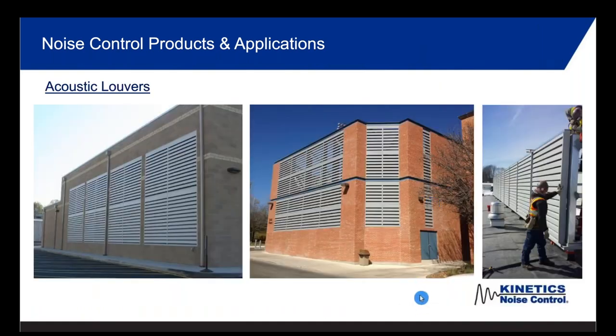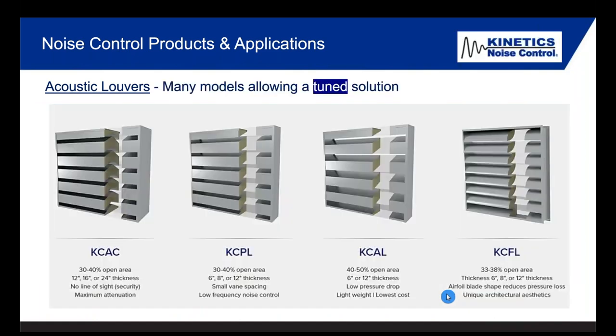Acoustic louvers, I love them. They're stubby ventilation silencers, typically anywhere between 4 inches deep to 24 inches deep, whether it's a generator room and you're filling the holes, whether it's an equipment yard with no top for cooling towers, or sometimes it's equipment on the roof and the architect really likes the look of these horizontal lines. So instead of using a solid barrier wall panel, they use that.